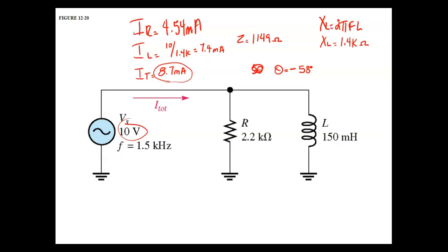And why? What's out of phase in a parallel circuit? Why do we have all these things out there? We have all these motors out there. What do motors consist of? I brought a stator in here for you, and it's just one big old inductor, right? You understand? How many motors do we have running out there in the industry? How many motors do you think they got at US Steel? And they're inductors. And they're trying to make the current do what? They're trying to make the current lag.